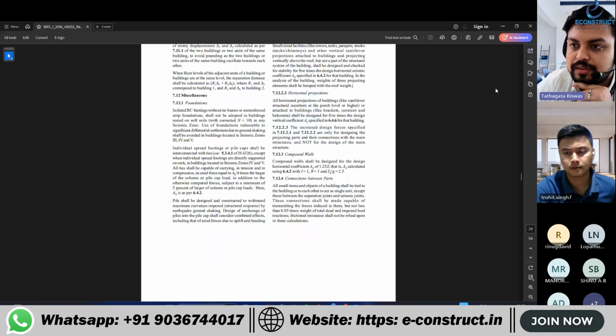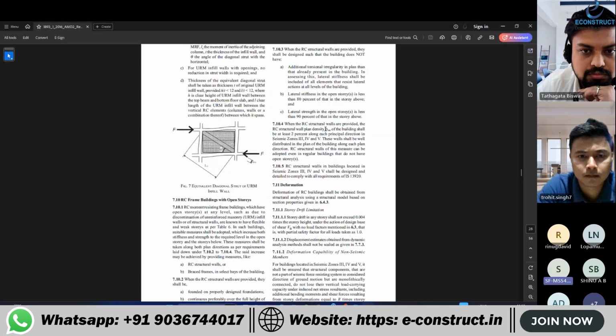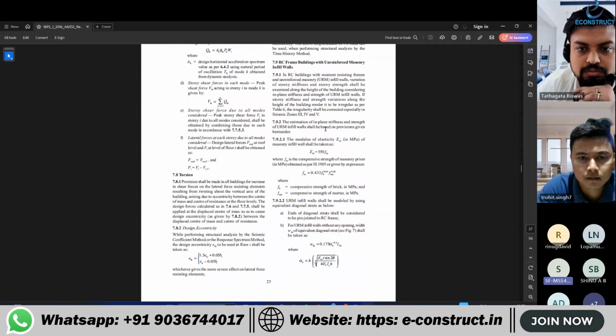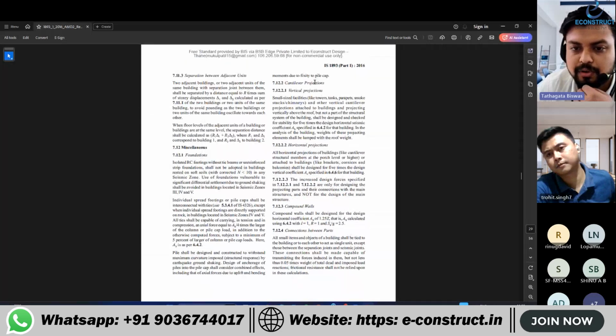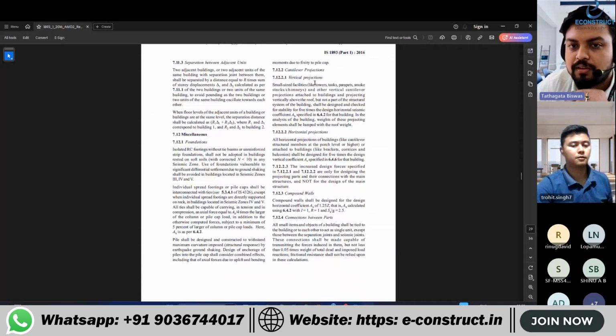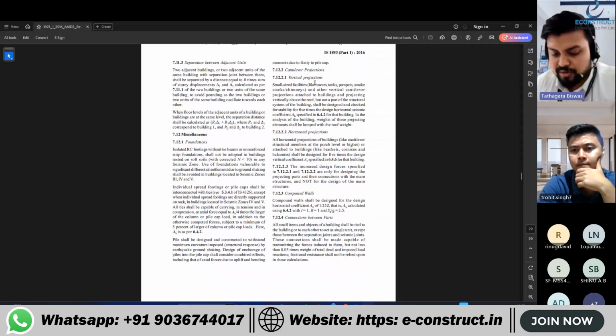Hello, sir. Yes. Sir, clause number 7.9 specifies that the strength and stiffness of the infill wall has to be considered along the height of the building. So the stiffness means we have to model these infill walls also? Oh, we have already taken that in the time period, in the static time period. So the stiffness is already considered inside the time period itself. Since we are not modeling it, that's why we are doing static analysis. Otherwise, that is not required.